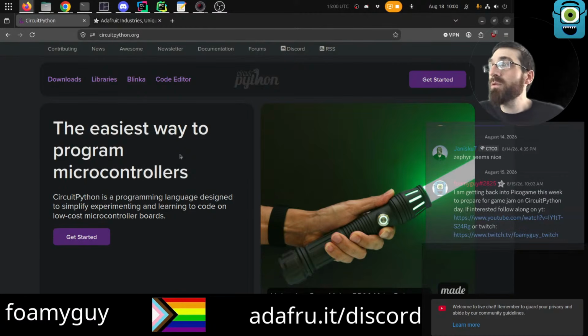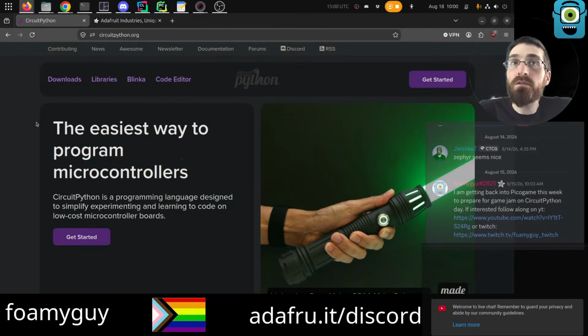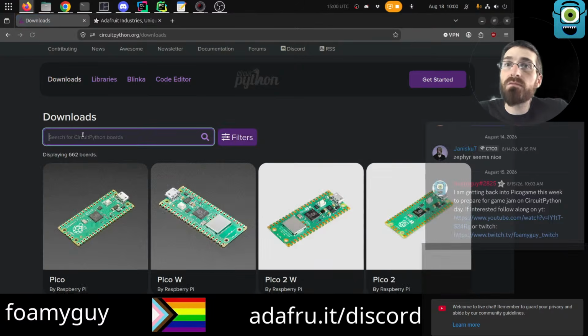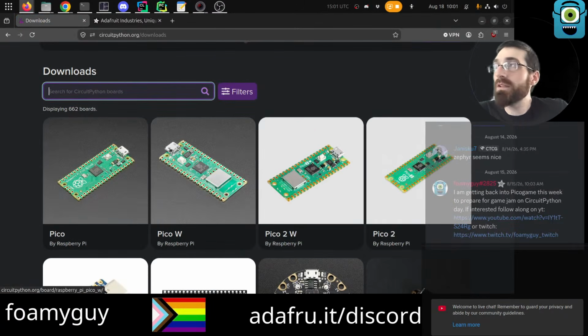If you don't know what CircuitPython is, this is basically a version of Python that is designed to run on tiny computers called microcontrollers. Typically, when you use CircuitPython with these devices, you'll plug them into your computer with a USB cable. They will usually have a little USB plug there for you. It shows up like a thumb drive, a mass storage volume. You can then edit a Python code file on that drive. When you save it, the microcontroller will interpret and execute the Python code for you, and your code can interact with whatever other electronic and hardware peripherals you hook up to your microcontroller.